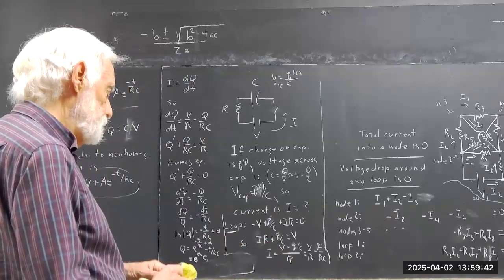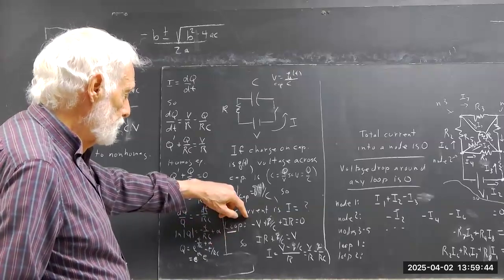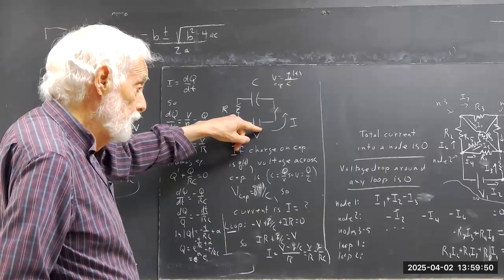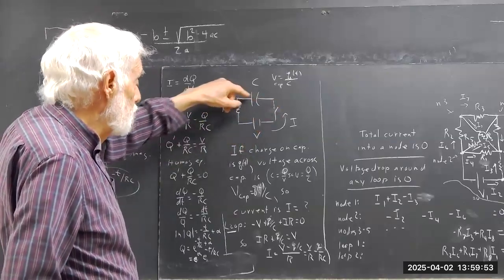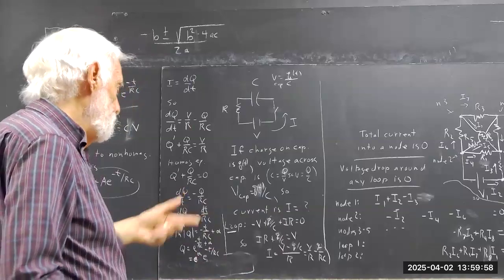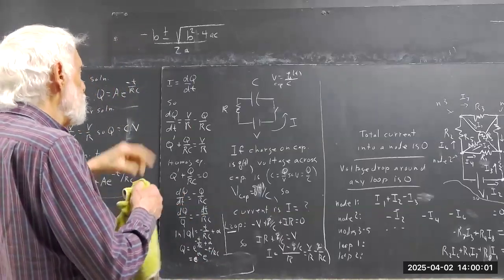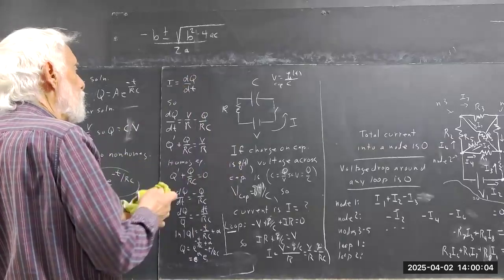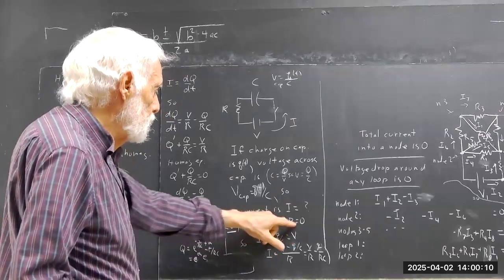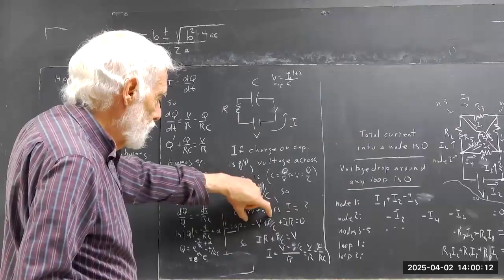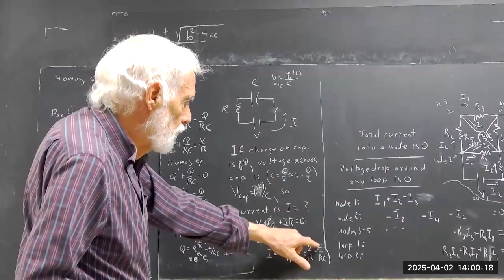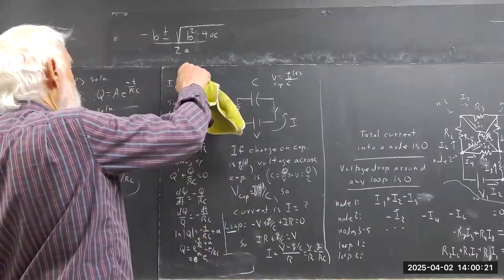And there we have the loop equation. Okay, go around the loop. Voltage drop here is negative V because the voltage rises. Voltage drop across the capacitor is Q over C. Voltage drop across the resistor is IR. So I equals this, which just comes from solving this equation, putting all this stuff on the other side. And you get V over R minus Q over RC. Okay.